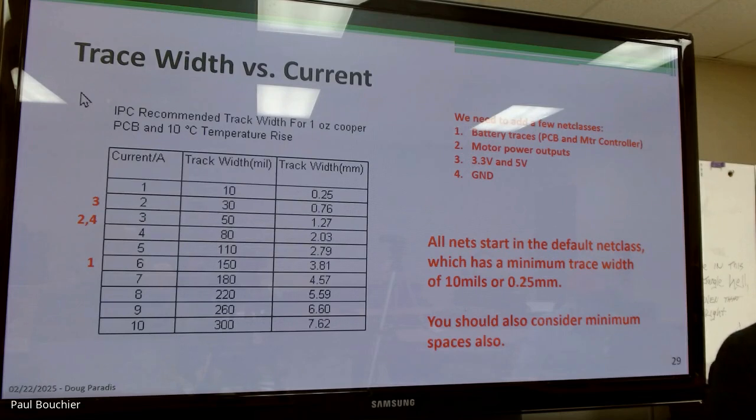This is me being, as a first cut, extremely pessimistic, but we have some limitations too, because the TB6612 module has spacings between pins of 2.54 millimeters. So you have to be careful, or if we make it too wide, we're going to end up encroaching on other pins. Anyway, here is the way I got it.